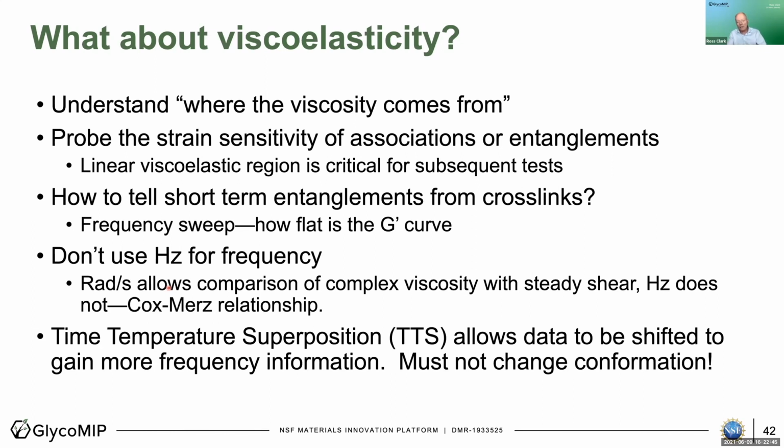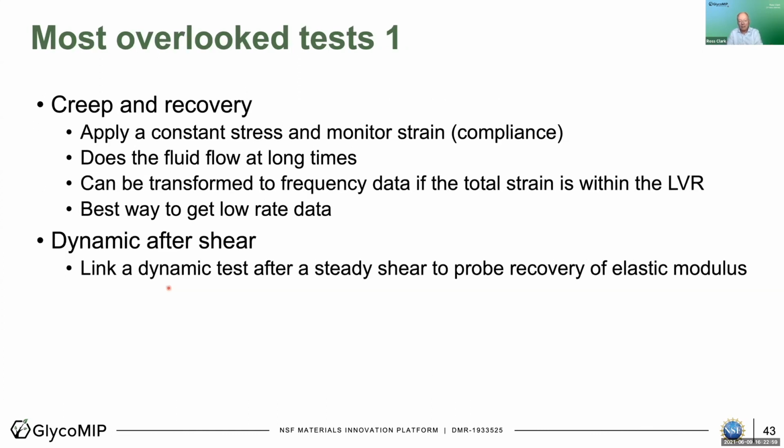And of course, time temperature superposition is a great viscoelastic tool to be able to extend the range of frequencies that I can measure. So it is a big benefit of viscoelasticity. What are the most overlooked tests? Well, creep and recovery.